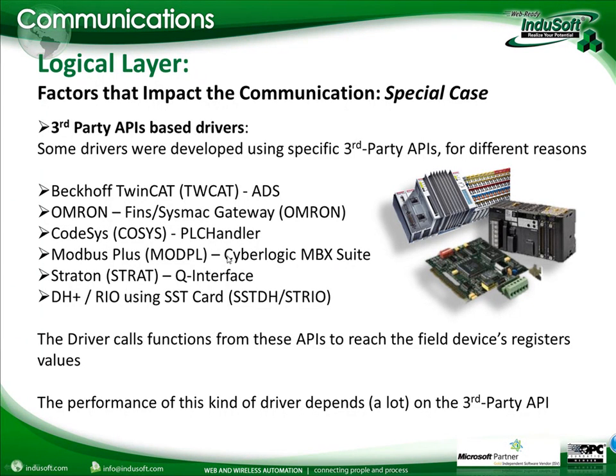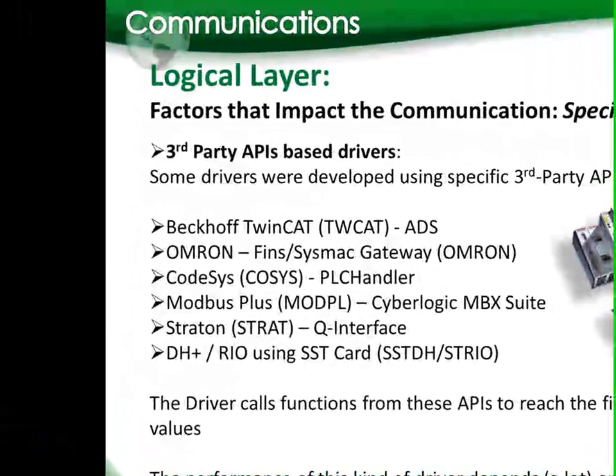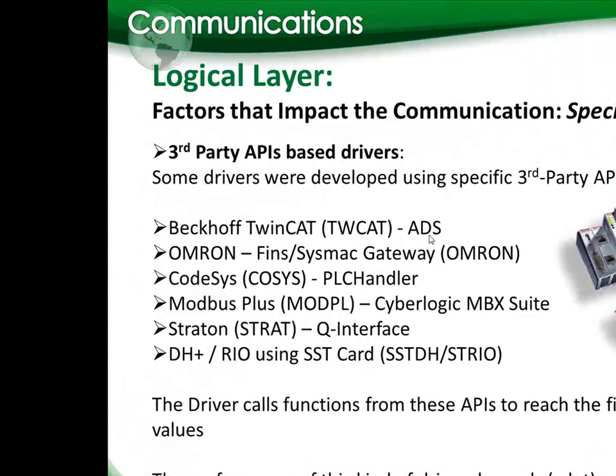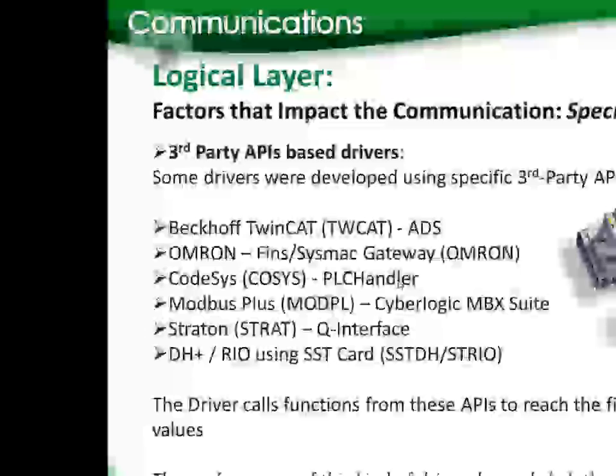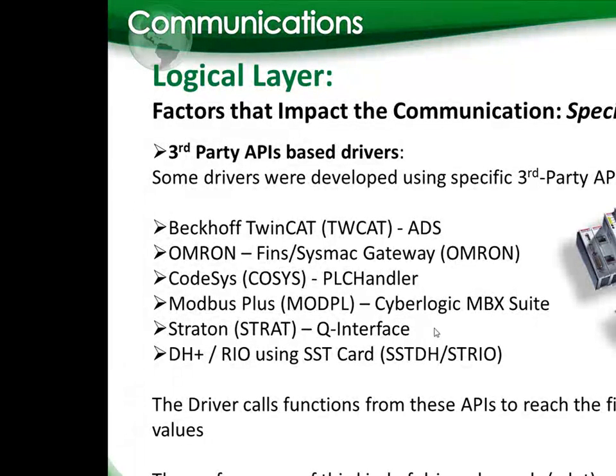We have the CodeSys based PLCs like the Wago or the Eaton Moeller PLCs. They also run CodeSys, so we go through the API from PLC Handler. So for some specific devices, we must have the API to write the driver. That's why there are some devices out there that we don't have drivers for, because we simply don't have those APIs to write the driver.